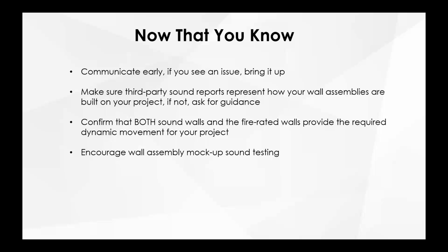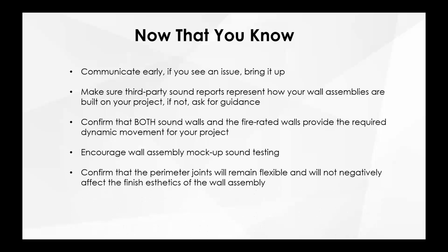Encourage mock-up sound testing. Again, you might think it's a big upfront cost, but in the end, it could save a lot. Believe me, that one contractor that had to remove the drywall and add RC would have wished they had mock-up testing done in the first part of the job. That contractor had to pay for all that, which is a real bummer. But if you have mock-up testing early, you could find out if it's performing to their liking or not, and then you can make adjustments.